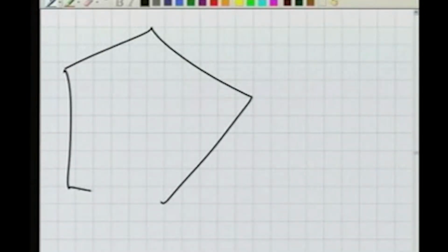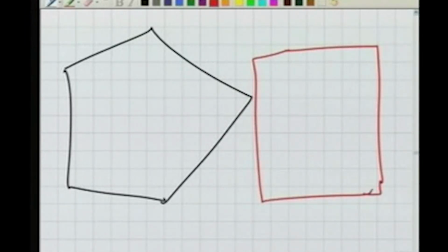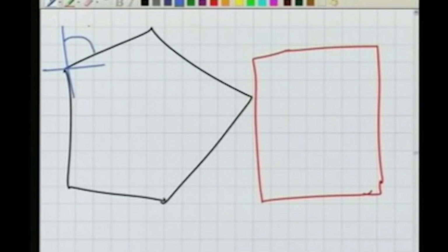Whatever method you use, if you are using CAD, you can plot it there in the CAD, or you can plot it on your drawing sheet, because you know all these basic things starting from any point. Let us say I can do one plot for you. There in the ground, the traverse was like this, and here on my drawing sheet I want to plot it. Why am I going to plot this for you? Because I am going to give you one more concept, or rather a tradition, a standard. There in the ground, for this line, for example, let us say the bearing was measured as 60 degrees. Now I want to take this ground onto my sheet.